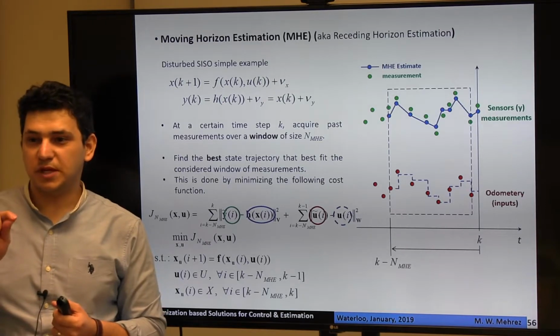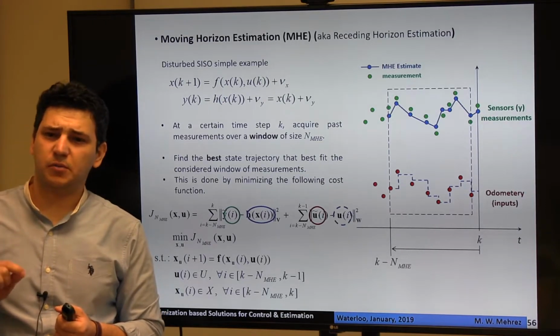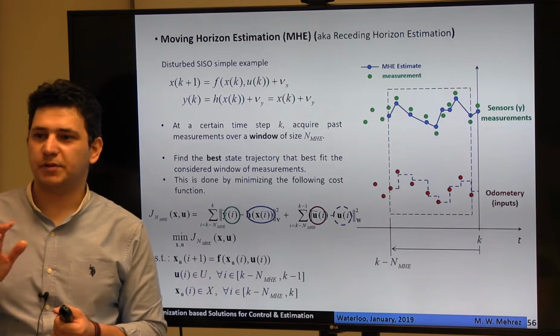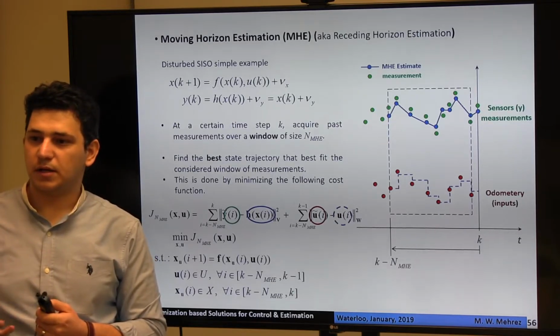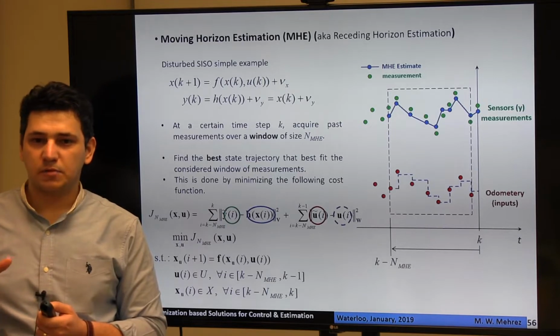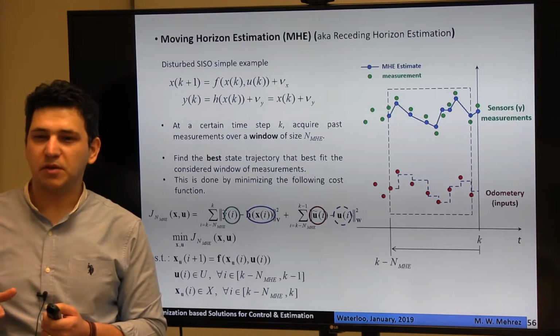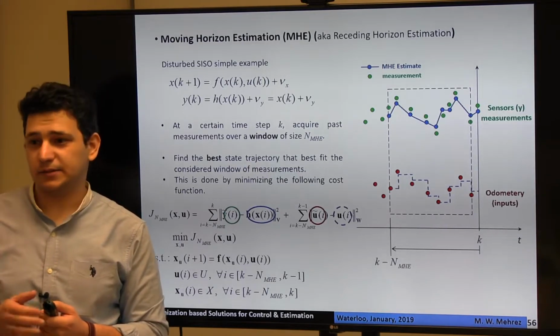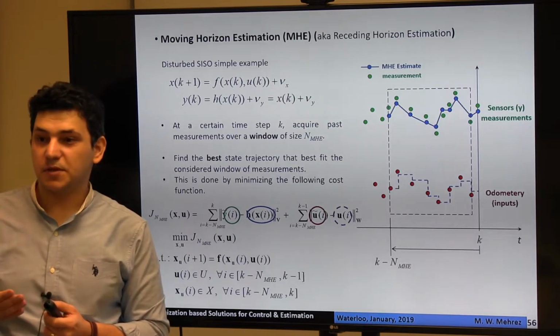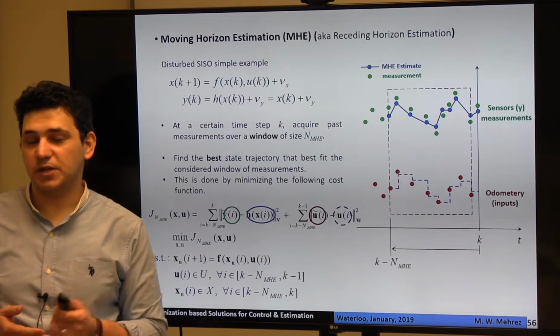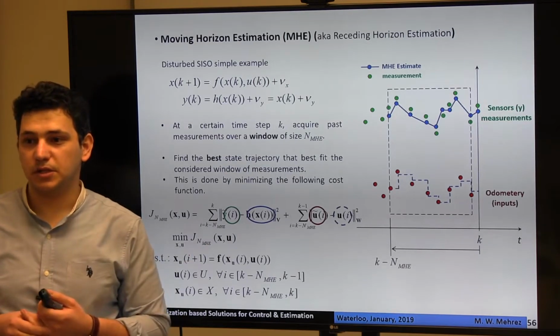Say you set the control actions V and omega to be, for example, 0.5 and 0.5. When you send this to your actual robot, the lower level controller may not apply these values exactly. So this becomes something that you would like to estimate, and you can actually estimate that using MHE, right?